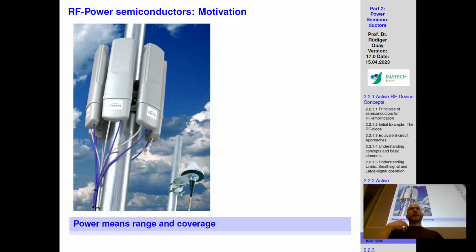And if you want to have higher bands, you have to go into higher modulation schemes. And having higher modulation schemes requires higher complexer modems, require complexer chips at some degree in your phones, and at some point you also reach the limit at how many constellation points you can distinguish in an eye diagram or whatever the case it is, and thus, you need raw bandwidth more. At some point, modulation will not help you.